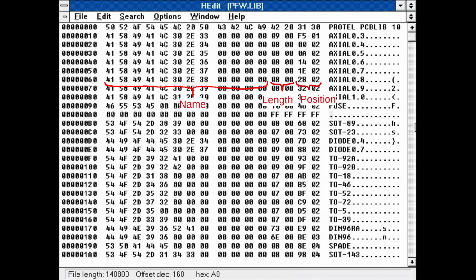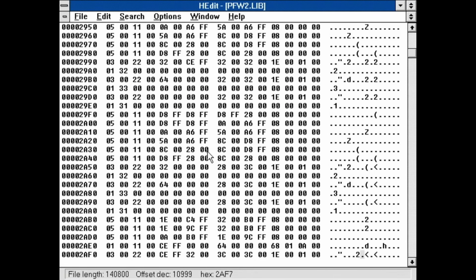Makes sense since this entire library format seems to be built on 16-byte chunks. The symbol itself consists of these draw commands. The one starting with 05 draws straight lines. The 03 draws a pad and has a second 16-byte block for the pad name, with the first byte being the length. 01 draws a circle. All coordinates are 16-bit signed integers and are measured in thou.